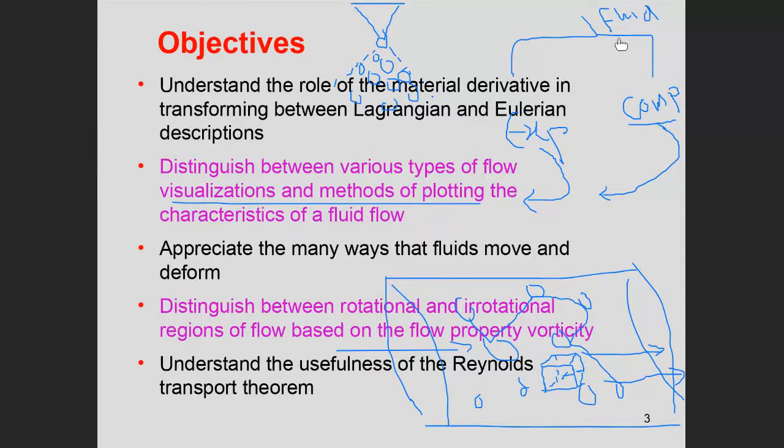If you want to study fluid dynamics, that is to say a fluid in movement, you can either go to experiment or computational. Both of them will give you data, right? There are two schools of thought, Lagrangian and Eulerian. You can follow each one, whatever you want. But mostly Eulerian. Lagrangian is useful where there are particles. You can model the flow with the particles, like spray combustion, right? Although Eulerian also is used, Lagrangian is more suitable, okay?